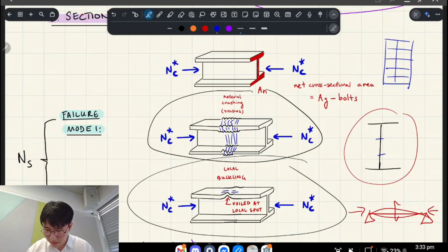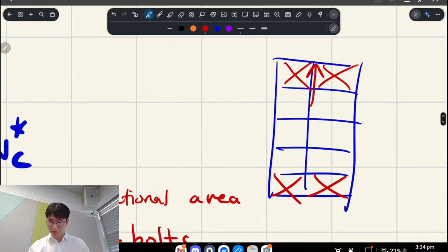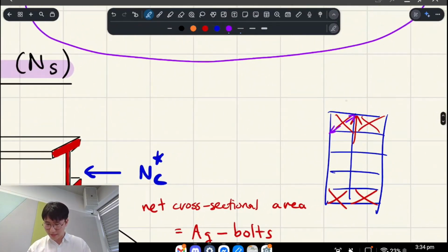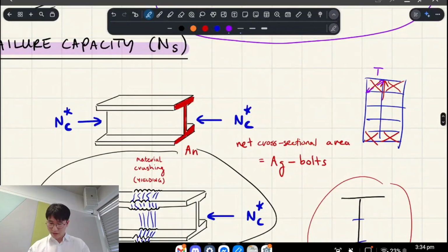You have bracing members on a roof, for example, where you want to stop wind forces that are hitting the edge of the building through tension. So this thing's bracing this structure. There's a lot to talk about there, but that's an example of where there'd be tension, right?